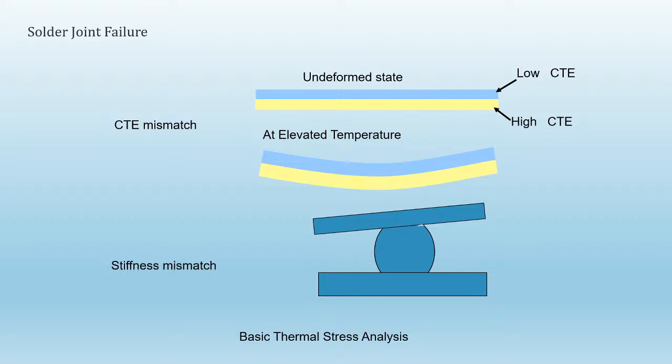For mobile systems, usually the power is fairly low, but the package is very thin. So sometimes, depending on how powerful your mobile chip is, you may need to do solder joint analysis, but also drop is very important for mobile reliability. But today we're going to stick with one topic: thermocycling induced solder joint failure.